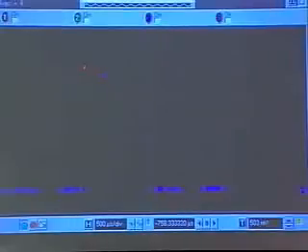Notice that initially the dependent current source is off, so I move straight down. Nothing happens until I hit a value at which the current source begins to come on, and then I begin to see a drop in the output as the current source begins to conduct current. You see that? As I increase the voltage Vi, boom, you see the huge drop. Notice that for a small change, I'm now getting a big drop in the output.